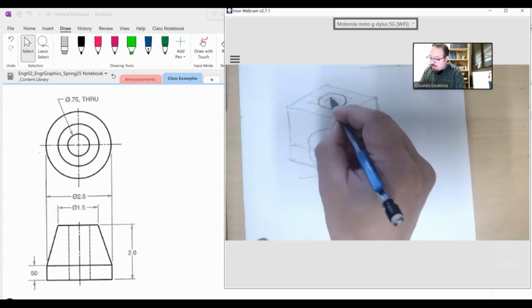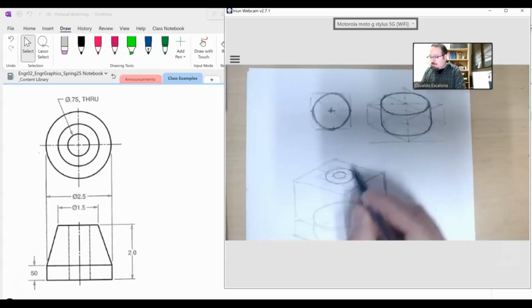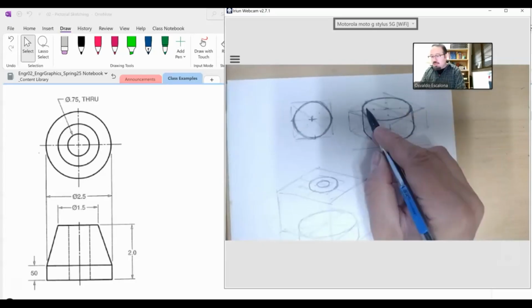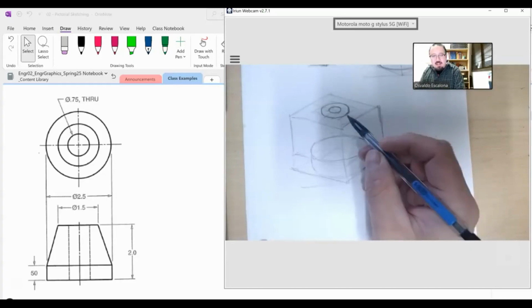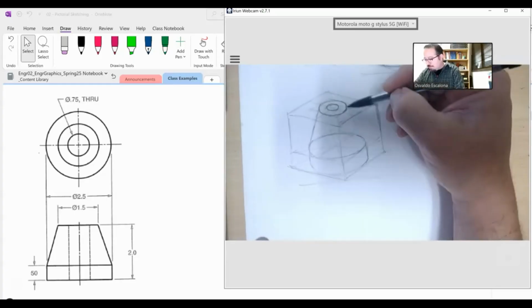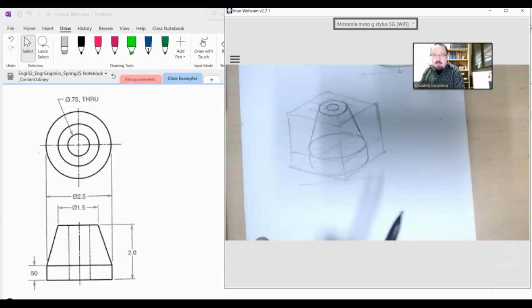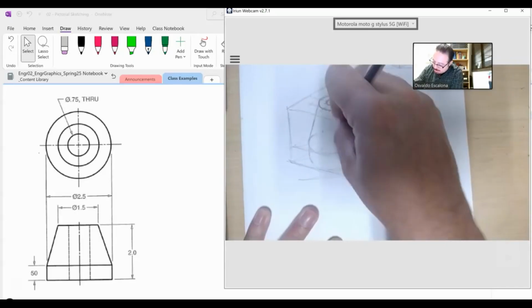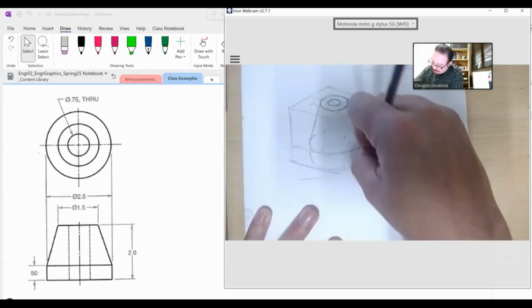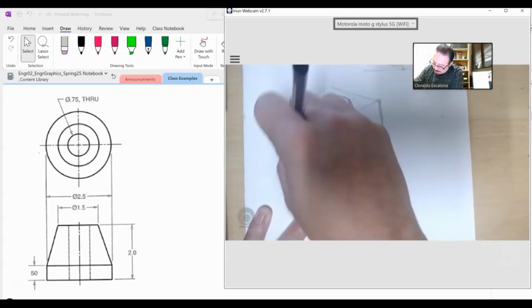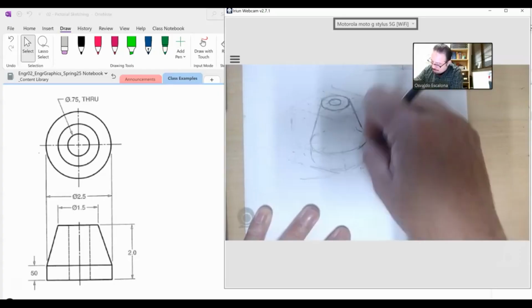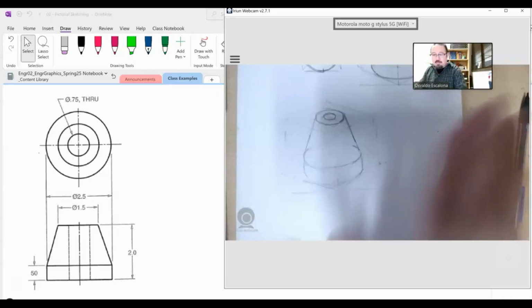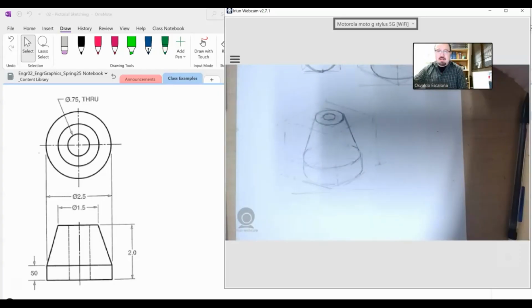You will make an arc, same concept. Make a diagonal, use the same way you did the other ones, diagonal, split into 3, and then you connect sideways, from here to there, from there to there, and then you get rid of everything else. Because remember, you do not have any hidden lines, and you also don't have a square that defines everything else. Boom, boom, boom.